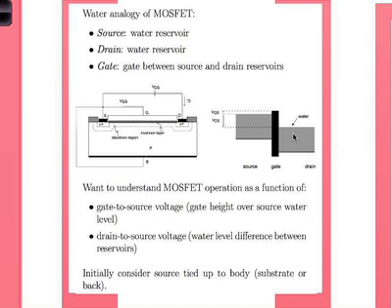Okay? The drain to source voltage, which is this level to this level, is the water level difference between the reservoirs. Okay? If the drain to source voltage is 0, of course no flow happens, irrespective of whether the gate is on or off, right? And if the drain to source voltage is negative, flow happens the other way. Okay? So keep those pictures in mind.